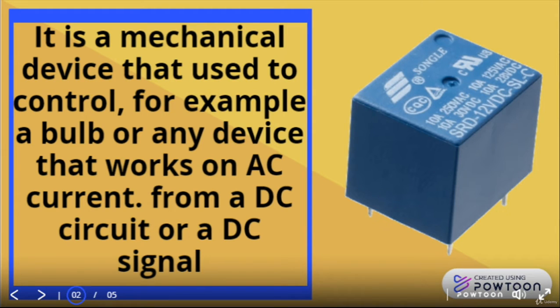Okay, the relay is a mechanical device. We use it to control a bulb or any device that works on AC current, using a DC circuit or a DC signal. So that means this component is between two circuits, a DC circuit and an AC circuit. We give this component a DC signal, and this DC signal will allow us to control the AC device, or the device connected on the AC circuit.